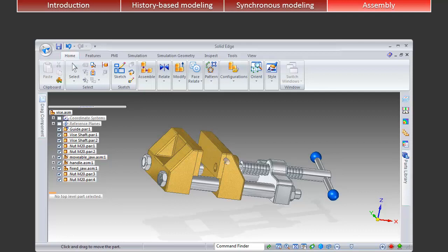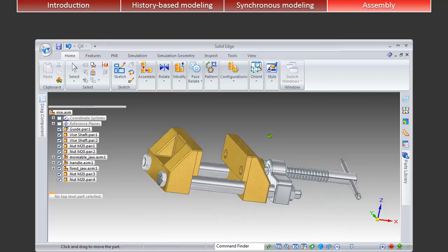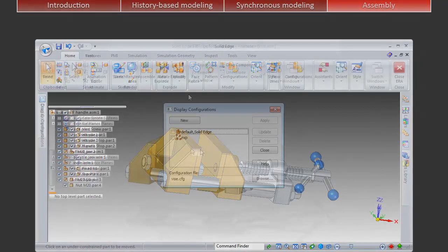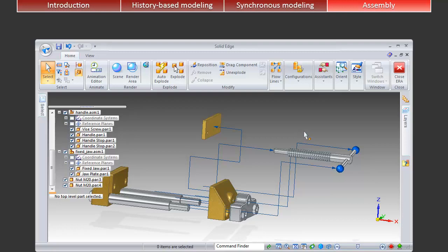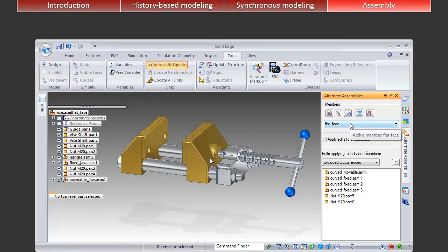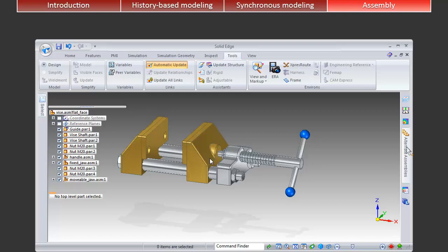Solid Edge lets you analyze and animate the motion of under-constrained components, including collision detection. You can also define motors to simulate mechanisms. You can calculate physical properties of assemblies, build bills of material, and explode, render and animate assemblies for complete product documentation. If you have used SolidWorks configurations, you will find their counterparts in Solid Edge families of assemblies, which define similar members that vary by well-defined and consistent sets of parameters.